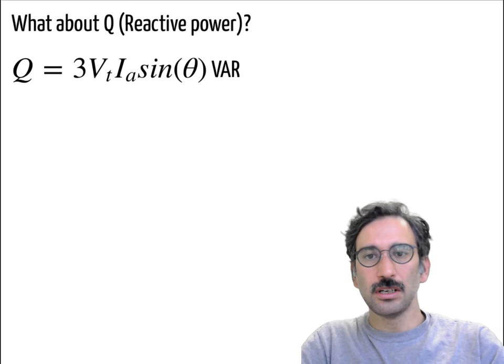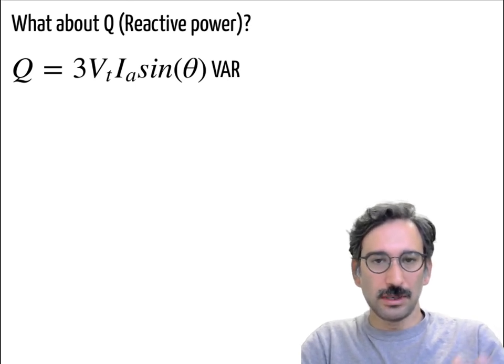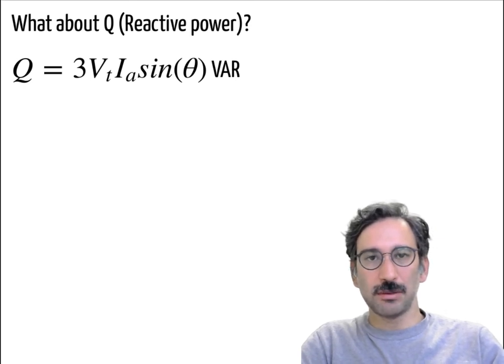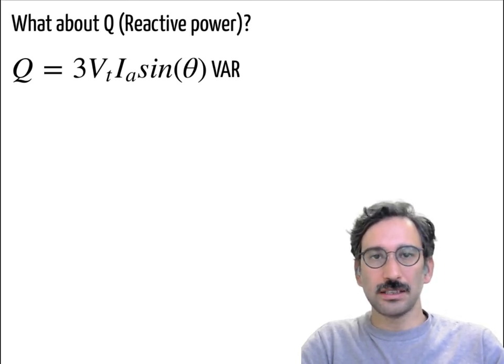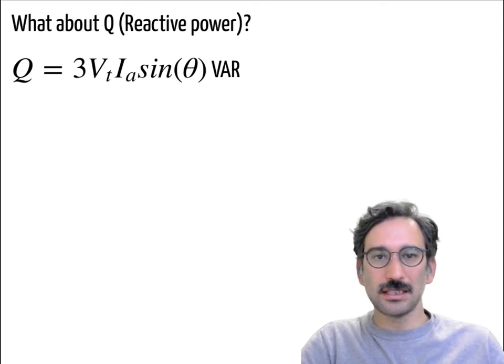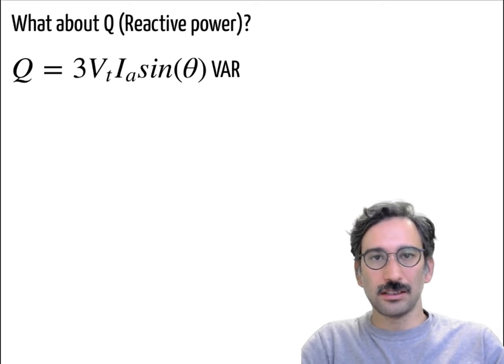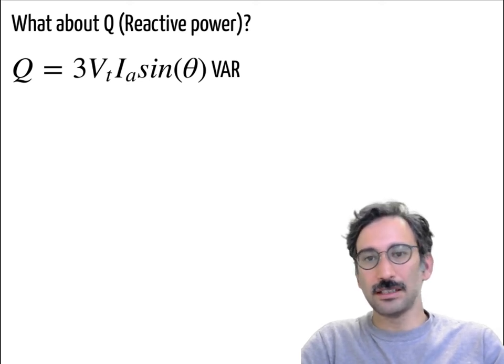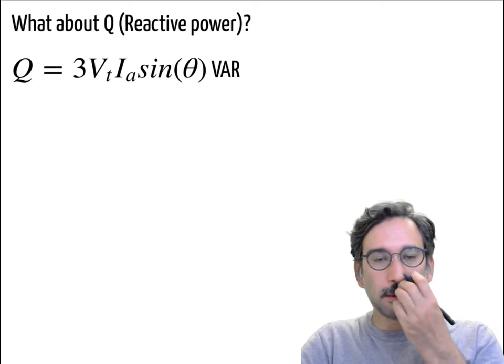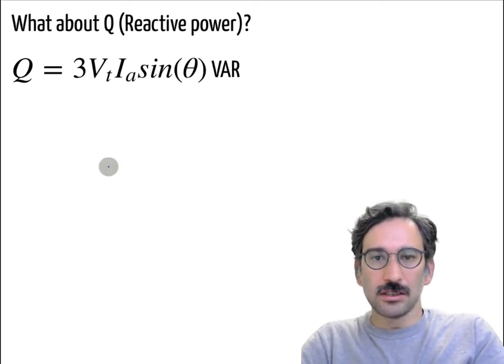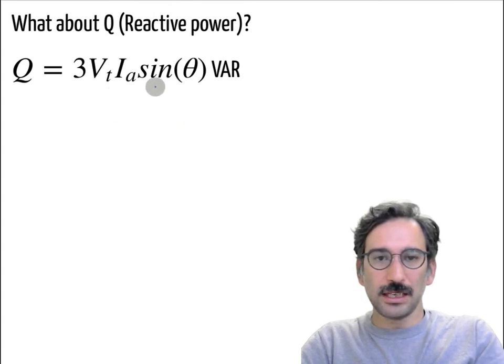Anyway, real power was Vt Ia cos theta, and similarly reactive power, if you remember from previous years, was Vt times Ia times sine theta, right? So if it is at unity power factor, theta will be 0 and there will be no reactive power. Actually, power factor is the definition of real power to the overall apparent power. Anyway, how can we obtain that relation?